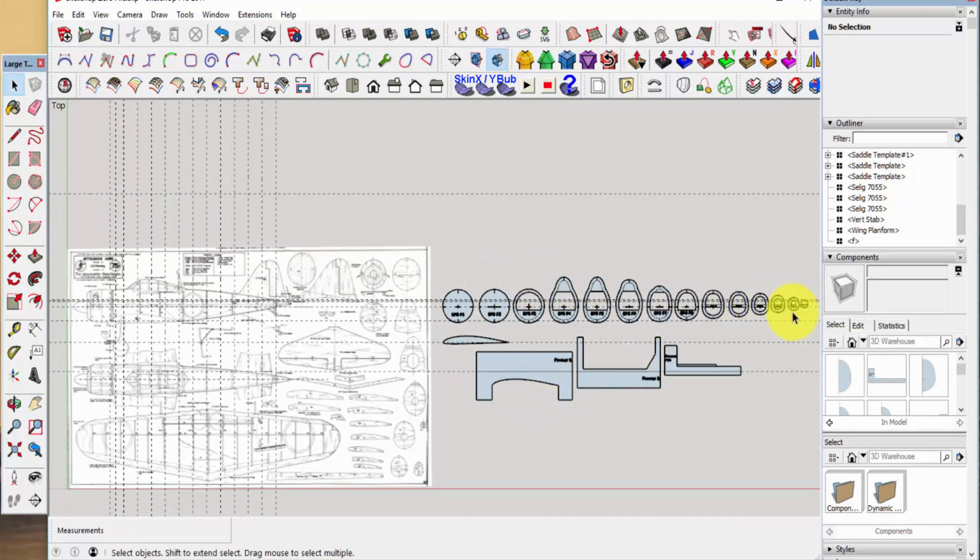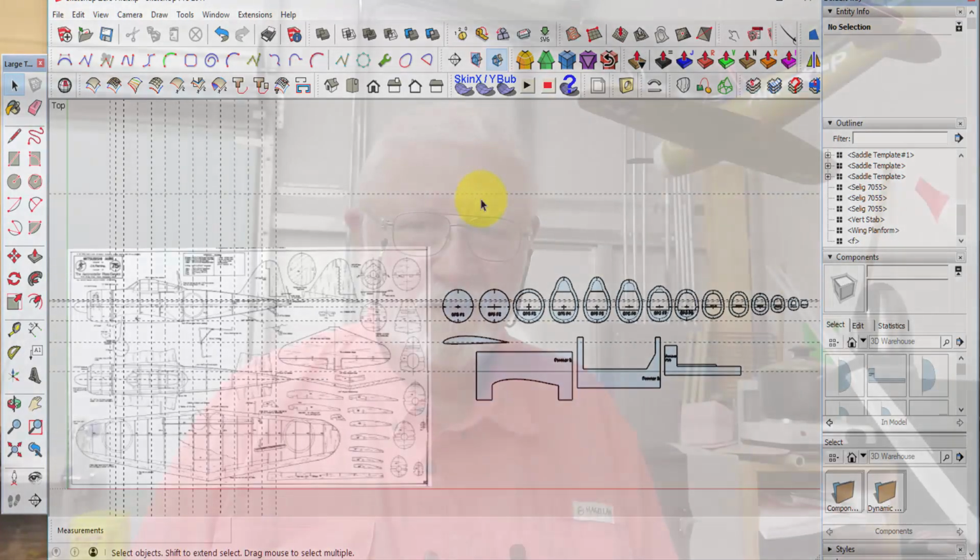We have all of our formers, fuselage formers, to cut our sections with. When we stack those up and bond them together, we have our three templates that we're going to use to cut the wing saddle, whether you do the cockpit or just the hatch, our hatch template, and then the final template back here for the horizontal stab.